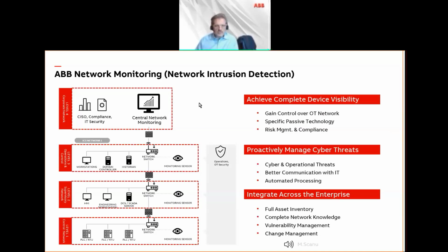Another important topic is that the type of network monitoring system that you use should also have a sort of library that is capable of understanding which protocols are normal for you, because maybe each and every control system has its own protocol. For example, we use MMS to communicate between the server and the CPU, or we have the RNRP communication to maintain the redundancy in the network. We have PROFINET communication for other systems.